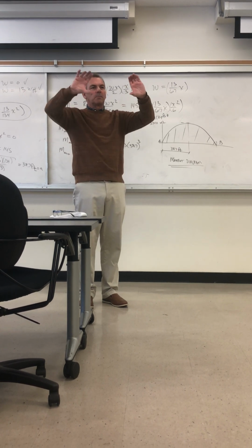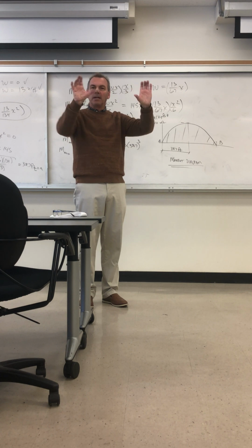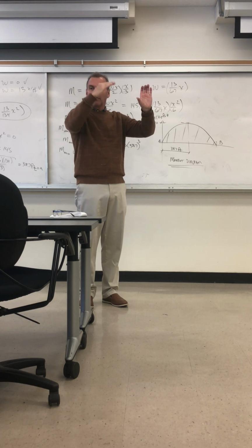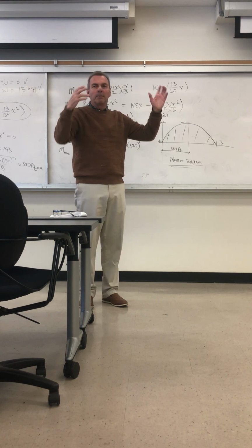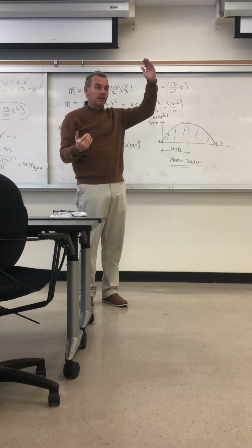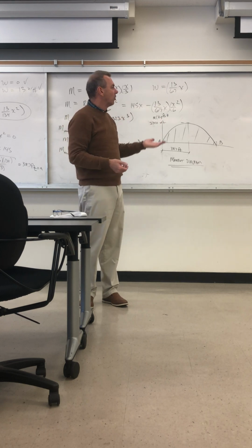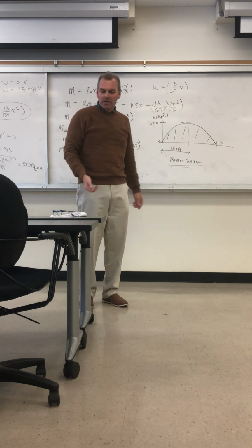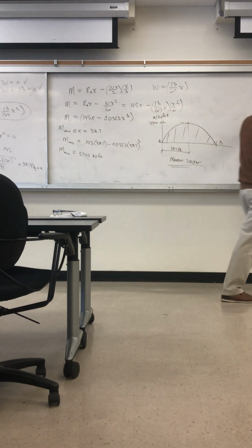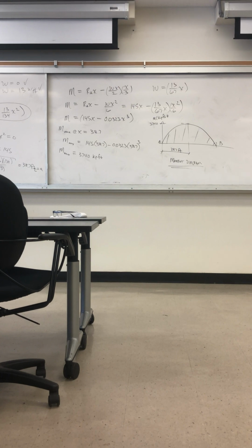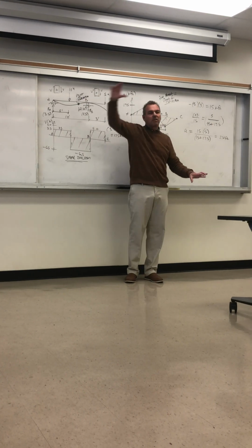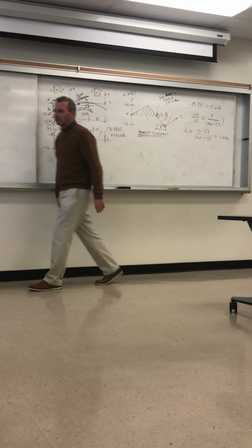When the moment switches, when it's bending like this over a support, negative bending, now the concrete is in compression on the bottom fibers and tension on the top, it cracks, multiple series of cracks, it opens up, and then the main steel reinforcement in that case has to be in the top of the beam, not the bottom. And so knowing where it switches from negative to positive bending is very important. In a bridge structure, you have a lot of reinforcement down in the bottom, and then here it would be all the heavy longitudinal steel reinforcement at the top. And as you go through this point, there would be a transition. You'd see the reinforcement changing from one side to the other under this load.